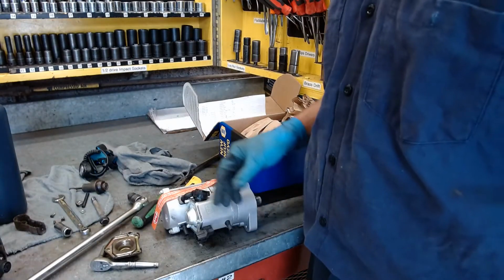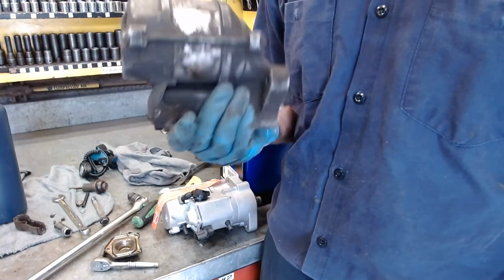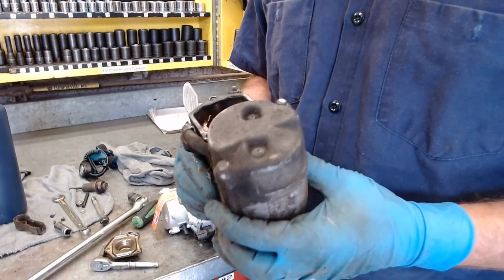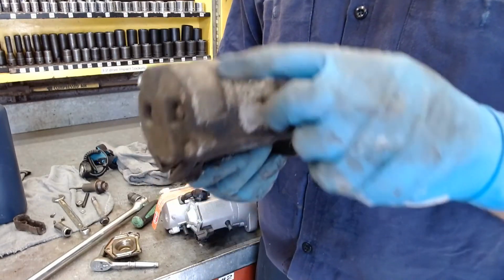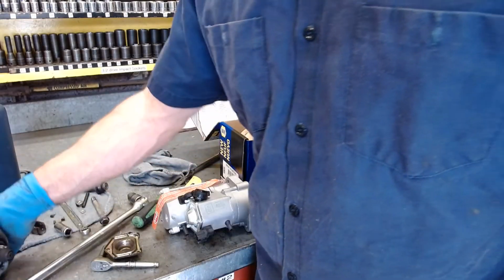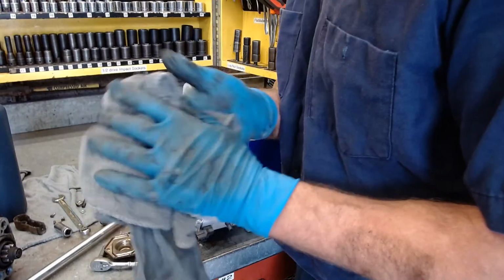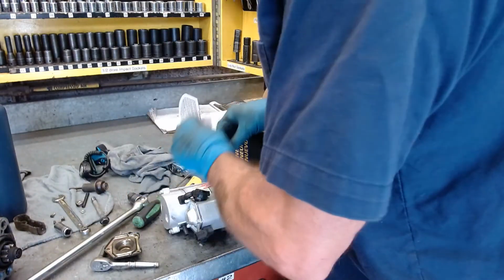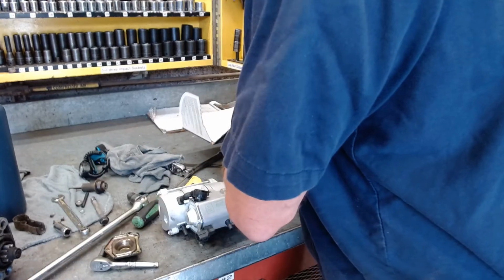Okay, I'm going to make the decision to put the new starter in because I do have another one of these Densos, but it's not the exact one. And the other thing about this is I can clean these contacts up, but I haven't done anything for the starter brushes that are inside. So in this case, I think I'm going to go ahead and put the new starter in because I depend on this truck and I lend it out a lot. And I don't want anybody to be stuck on the side of the road.